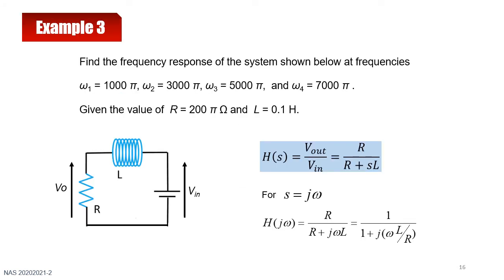Okay, let's have another example on circuit analysis. In this case, you have a series of R and L in the circuit. As mentioned earlier, you need to convert the given circuit into an S domain circuit. So this is R and L, and this is the source. Please take note which one is V in and which one is V out. In this case, you have the V in S domain, and L becomes SL, and R stays as it is.